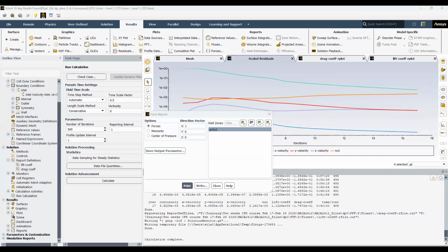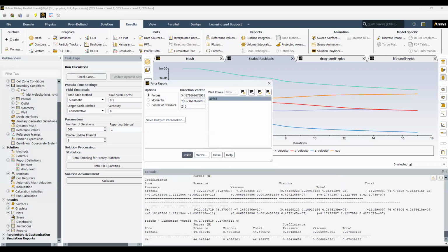this value will go in the x component. The cos component will be in the x component for the drag coefficient. Okay, and the same 10 degrees, and the cos component will go into the y component. Okay. So the drag coefficient is 0.67. It may not be a correct value because we have run the simulation only for 20 or 17 iterations.